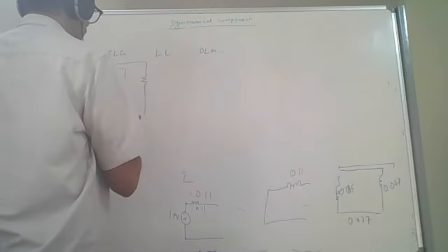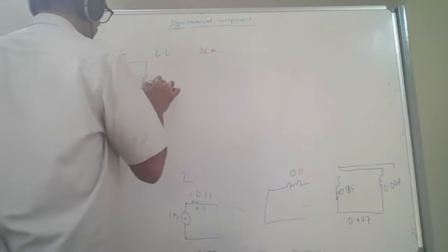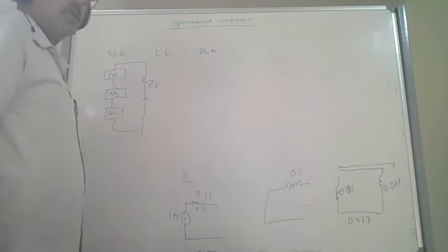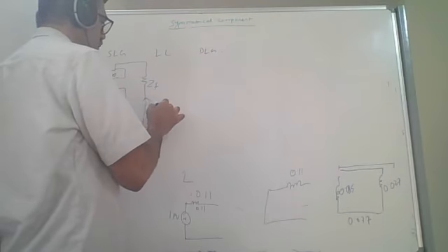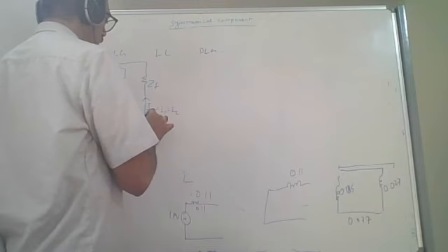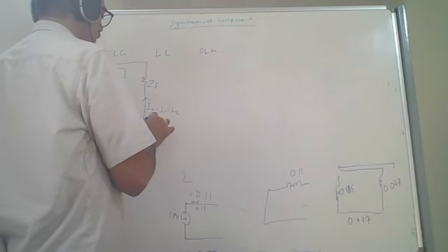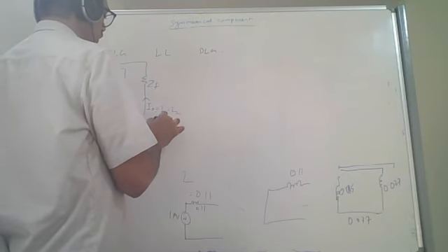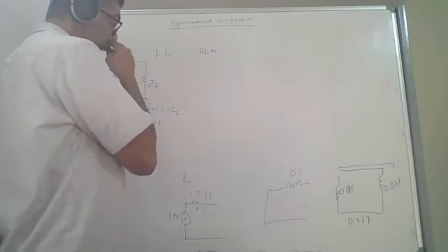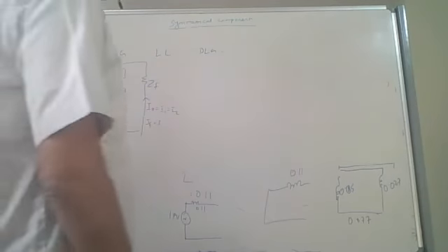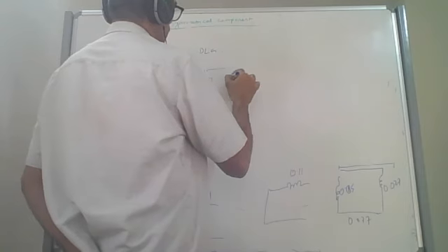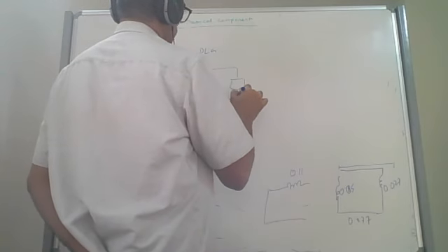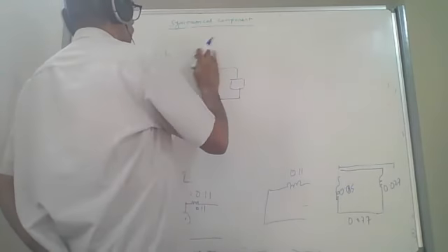And here is the fault impedance ZF, and that will give you the current. Then you have to multiply. That will give you the current, which is I0 equal to I1 equal to I2, and the phase fault current will be 3 times this one. And if it is a line-to-line fault, you have to add the positive and negative in parallel.